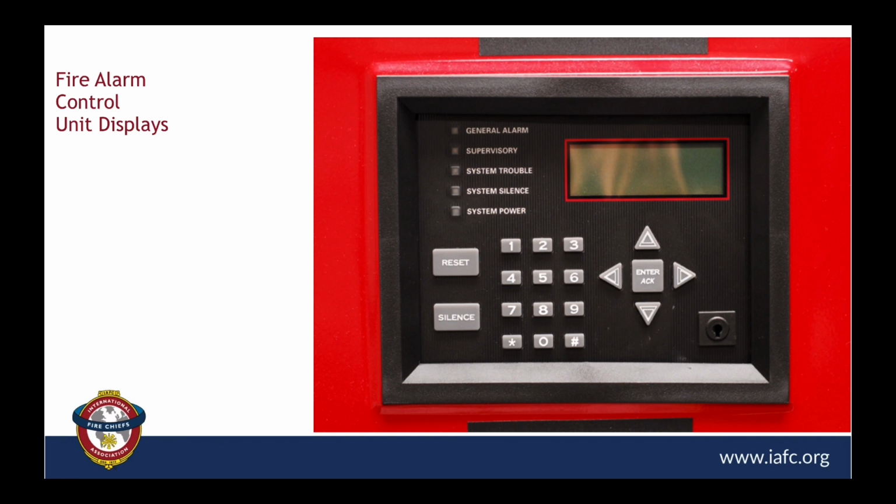Also, it's going to drill down and give you the information, for the most part, of whether it's a smoke detector that's causing the alarm, or a water flow switch, which I know might change your technical approach to this, or if it's a tamper switch or something of a supervisory or trouble nature. So we'll try to spend our time inching our way through this as we go through the panels.